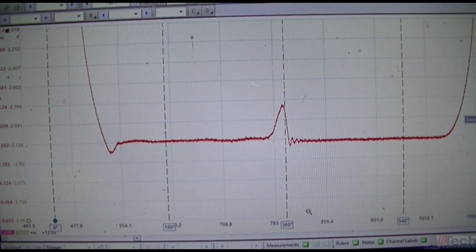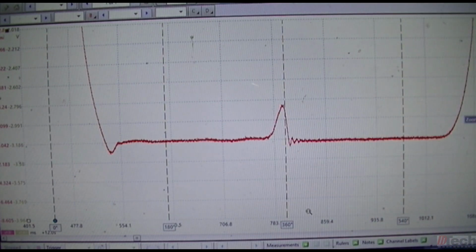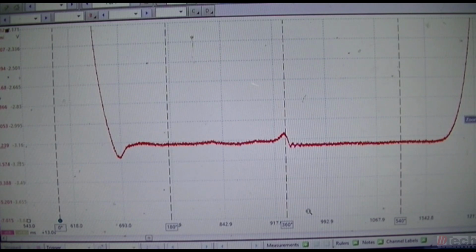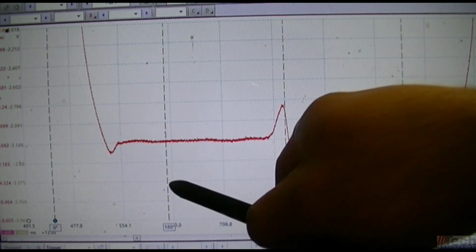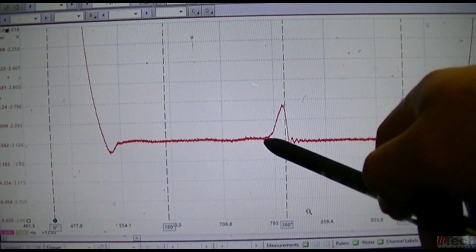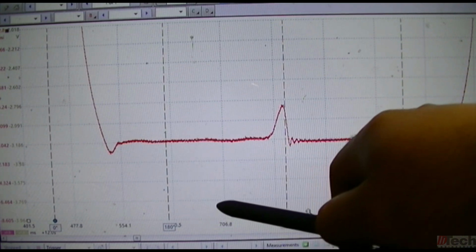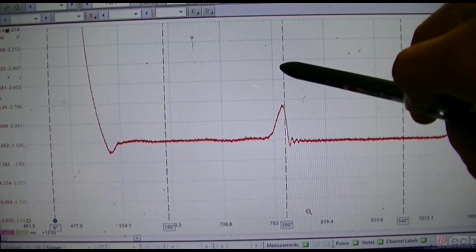Okay, so now we're zoomed in with the ruler set up, and we obviously get a better visual example of the difference in that rise in pressure. Typically and normally, from 180 to 360 is the exhaust stroke, and most of the time this will be when the exhaust valve closes as the piston's still in its upward travel towards TDC.